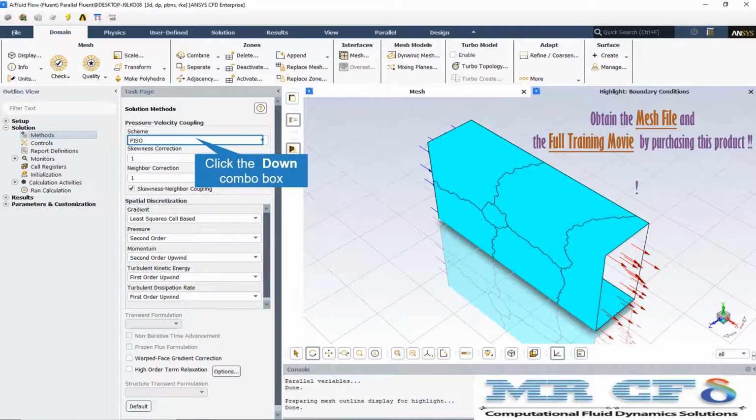One of the limitations of the SIMPLE and SIMPLEC algorithms is that new velocities and corresponding fluxes do not satisfy the momentum balance after the pressure correction equation is solved. As a result, the calculation must be repeated until the balance is satisfied. To improve the efficiency of this calculation, the PISO algorithm performs two additional corrections: neighbor correction and skewness correction.